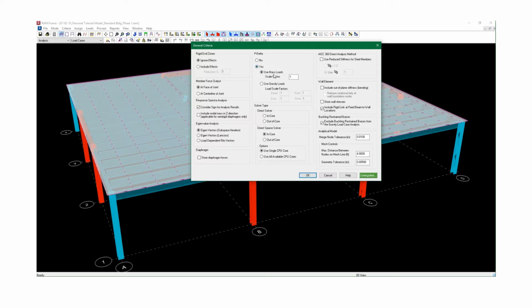And when you do include it, you then have two more choices to make at the very least in terms of the mass load factor, scale factor, or gravity load, which is what I typically use. And then I scale up my loads based on the load combinations that are applicable for the lateral load case that I believe to be controlling my lateral frame design.